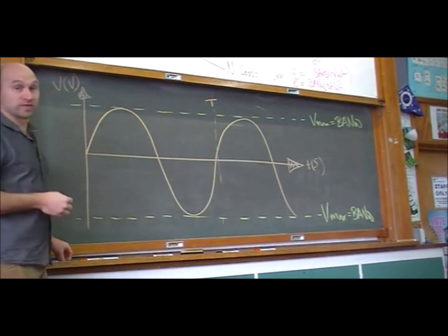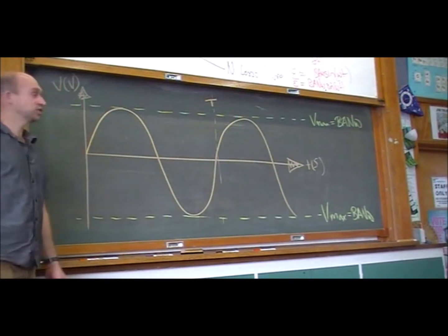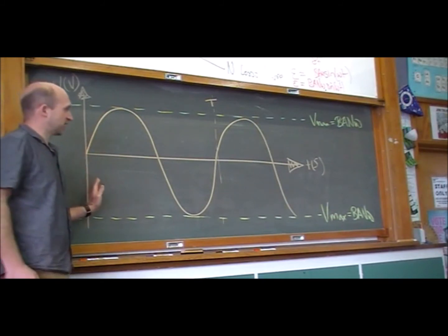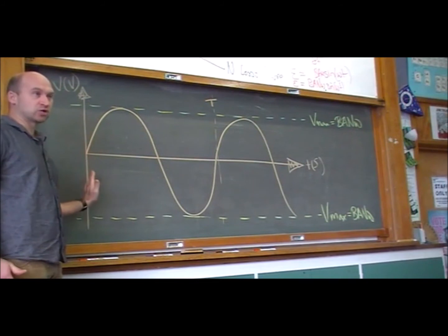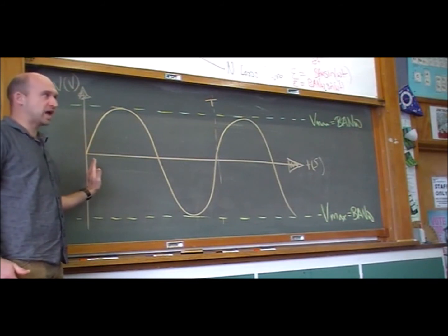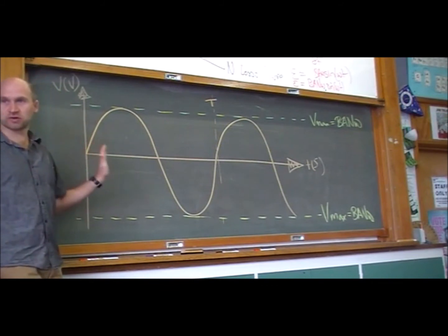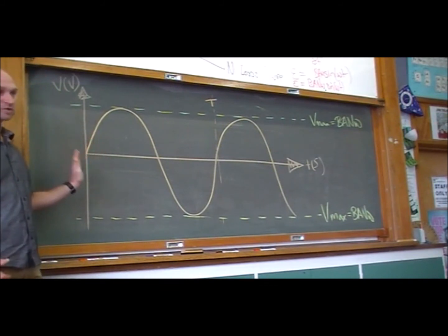So what does the output voltage from this thing look like when we turn the handle on it? Well, it follows a sine curve. So thinking about our picture, initially we had the coil so that it was at right angles to the magnetic field, and that meant that the flux through our coil initially was maximum.